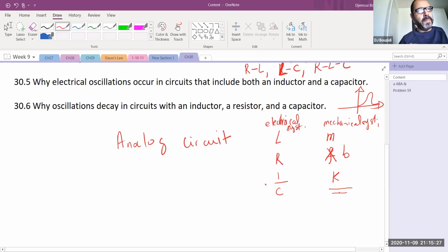So in this case, you have simulated a mechanical system using an electrical system, instead of wasting a lot of money building the actual building and then finding out, for example, that you needed a larger K or a smaller K, or a larger B or a smaller B, or that you needed to reduce the mass or increase the mass, or do something in the joints where the coupling needs to be different. In this case, you have saved yourself a lot of money by just finding that information from your analog system, the equivalent to it, okay?